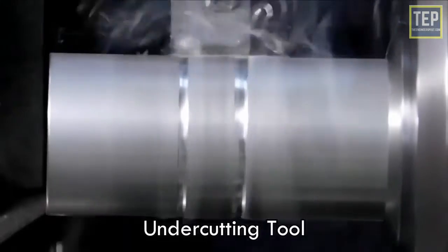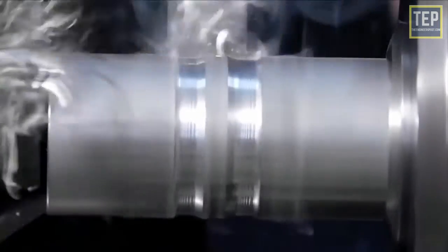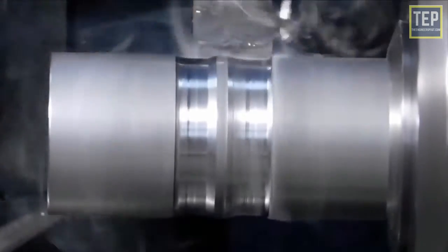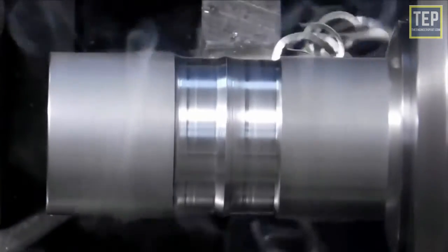Undercutting tool. An undercutting tool has a point and form of the cutting edge exactly similar to the form of the required groove. Clearance angle is given at all the sides of the tool. For the recessing groove cutting edge, the longitudinal feed is employed. The front clearance angle depends upon the bore of the work.